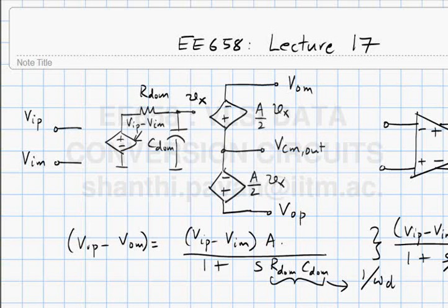When this becomes inadequate, I will introduce new artifacts in the model which hopefully account for things that one sees in a real op amp. As we discussed yesterday, the input of this op amp is going to be a differential pair. So the low frequency input impedance of the fully differential op amp is infinity for both common mode and differential mode signals. In practice, of course, there is going to be a small parasitic capacitance corresponding to the gate capacitance of the input transistors.